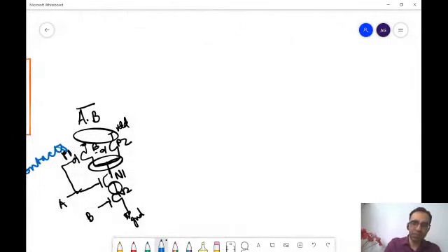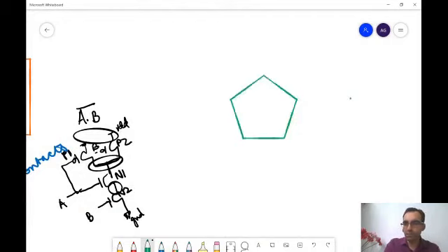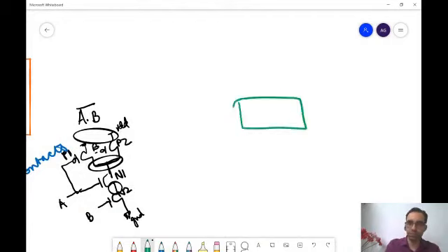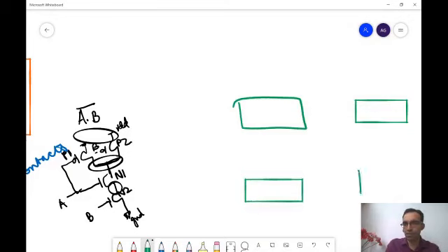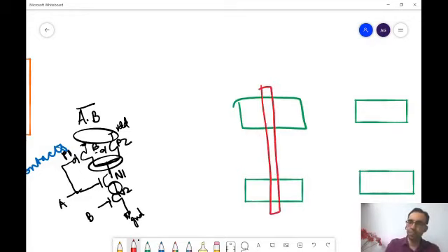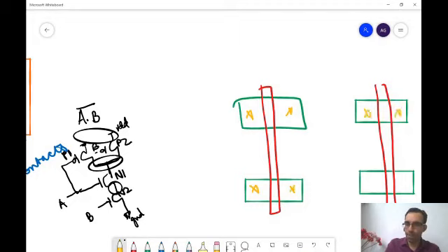You will get one transistor, another transistor here, and another transistor here. You will probably connect the poly like this, and like this again. And then you will put contacts everywhere and make the connection accordingly.